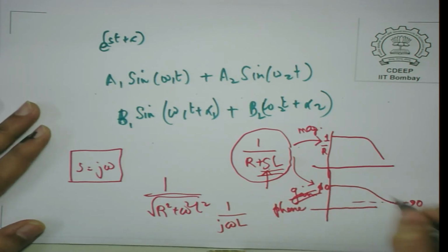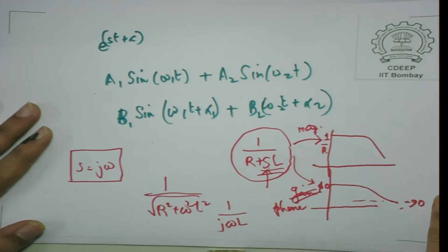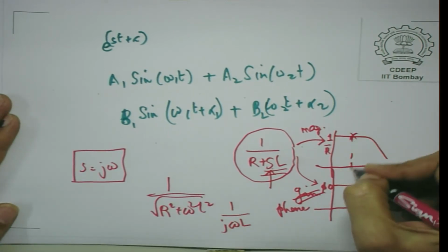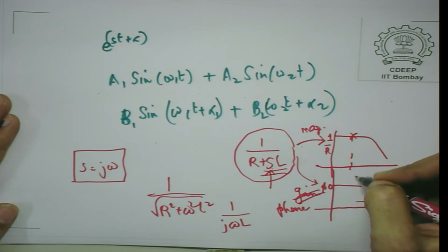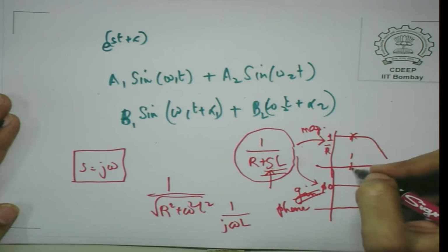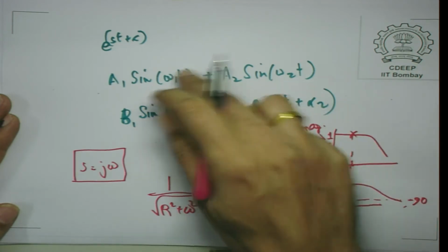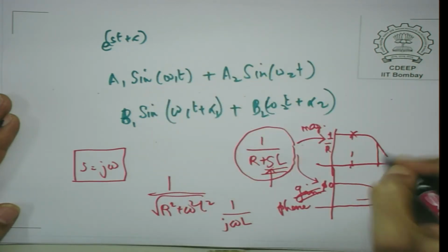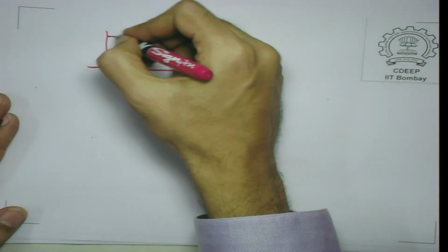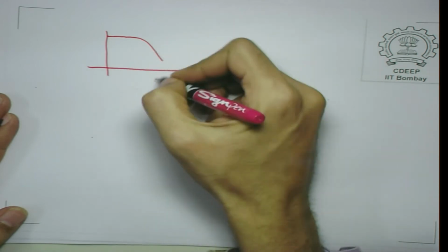This kind of curve is called a frequency response. What it really denotes is that any point here denotes the magnitude scaling which you will get in sinusoidal steady state if you have an input at that frequency. If you have inputs at 2 frequencies, you can of course get it from this curve, the input and the output. Something I will not prove here is that it is convenient to plot this magnitude plot on a log scale.